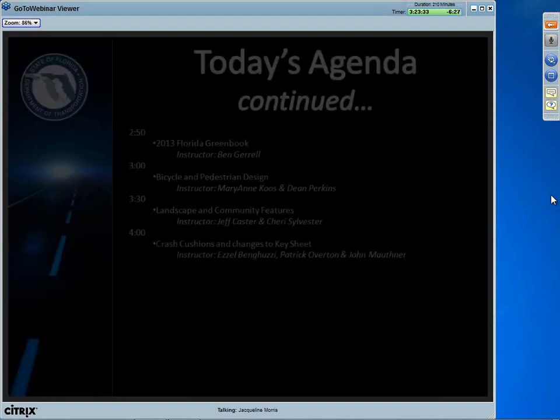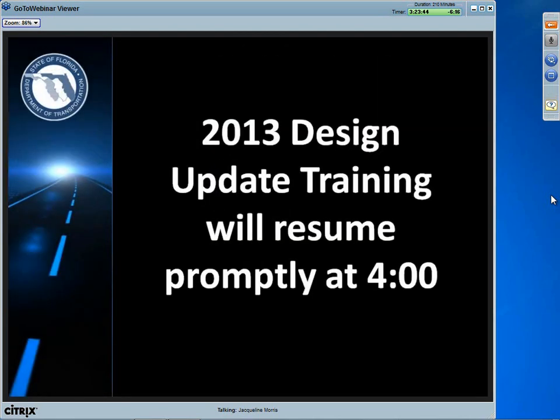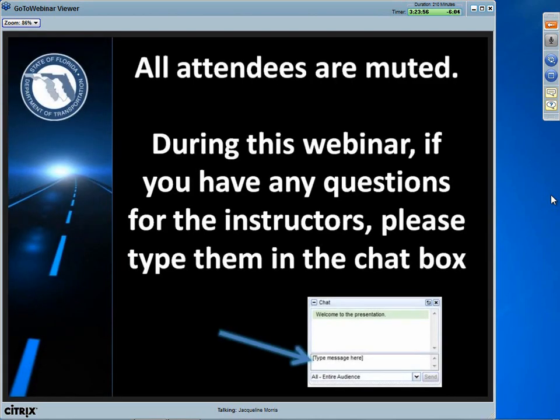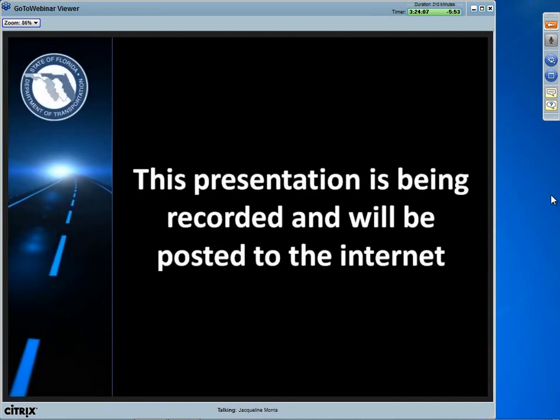The first question is, what aspects of the driveway should we seek to upgrade if feasible? And it follows in parentheses: grade, sidewalk cross slope, width, spacing. I think grade is, first of all, going to be very important, especially if it significantly exceeds a 2% cross slope. Width, you see that we're expecting to have this 4-foot accessible route. ADA would allow you to have a 3-foot wide accessible route. So if it's less than 3, that would be a very important point to work towards correcting.